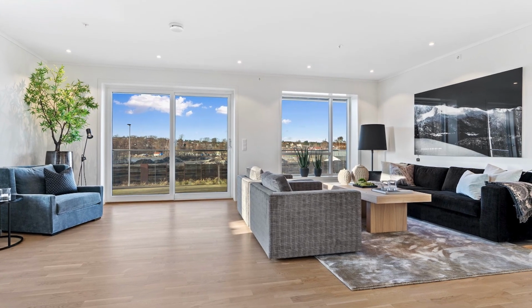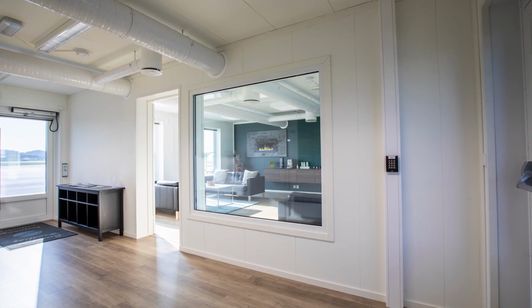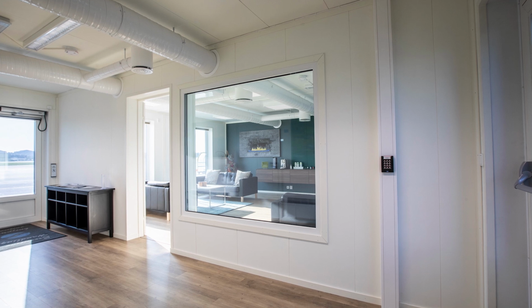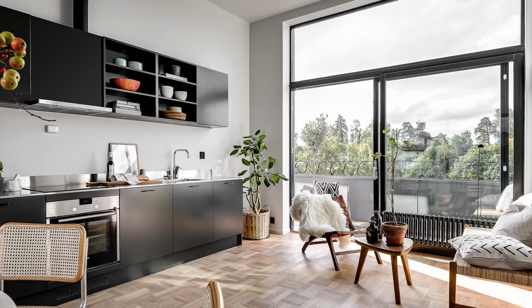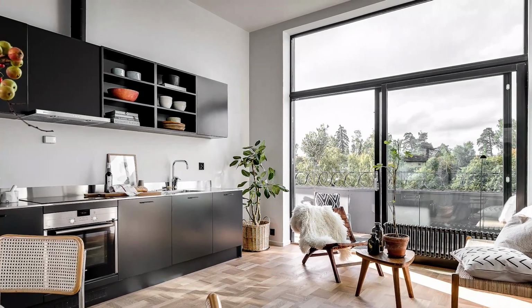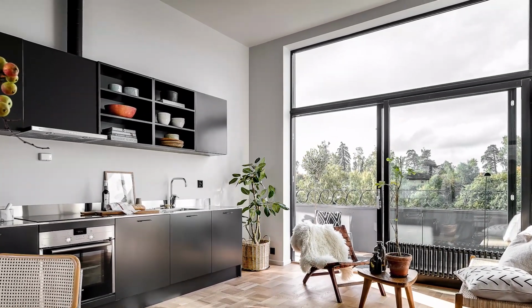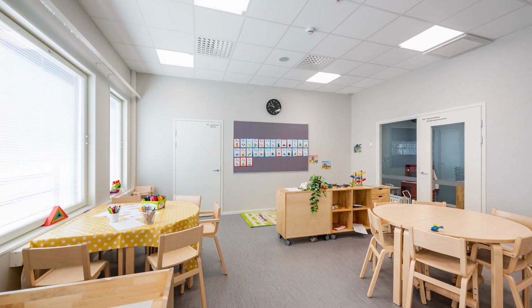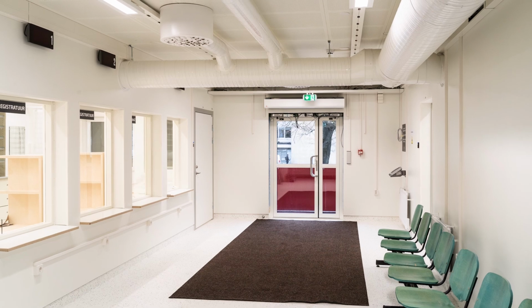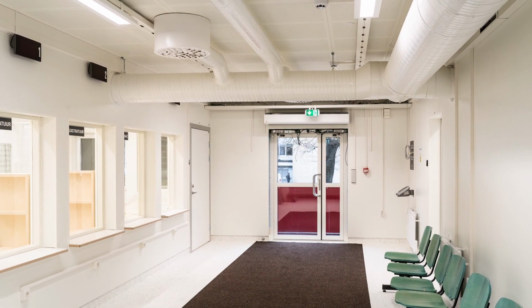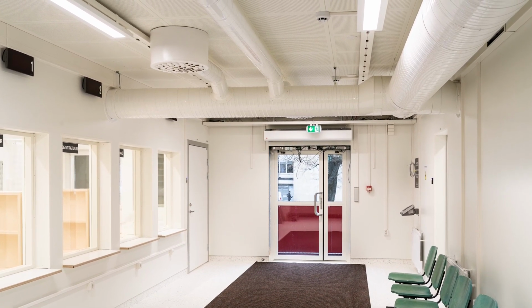Wallpaper is rarely used. In public buildings or dormitories, panels made of wood fiberboards with a finished surface have found use. The ceiling in a dry room, just like the walls, is covered with plasterboards that are painted. Additionally, acoustic suspended ceilings or wood fiber or metal panels with a finished surface are also used on the ceiling if needed.